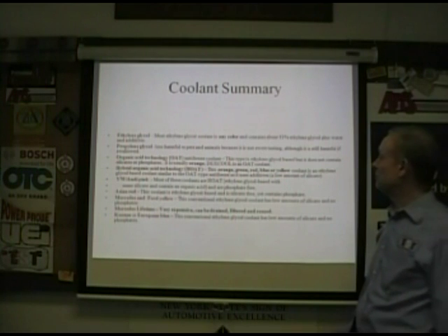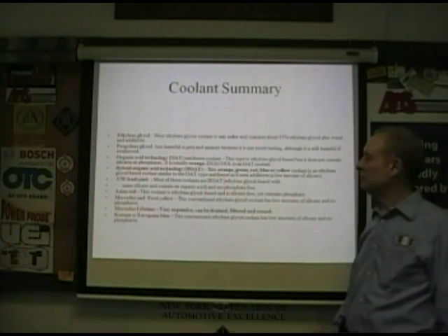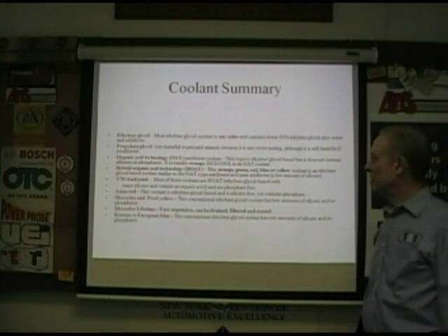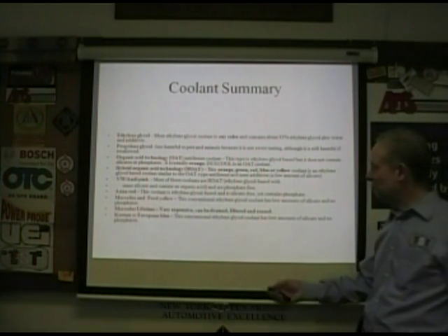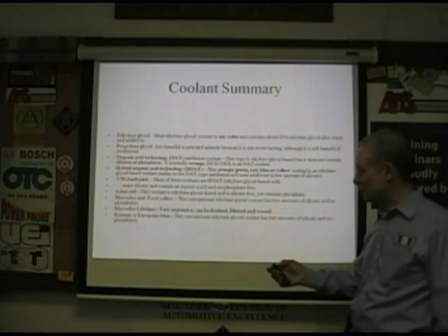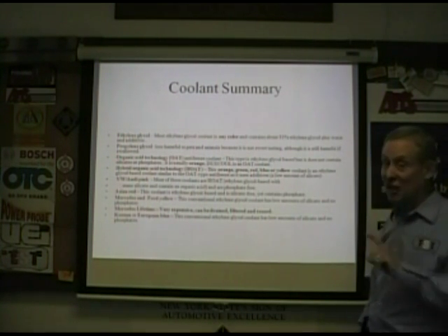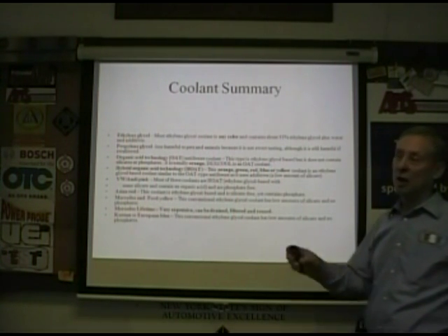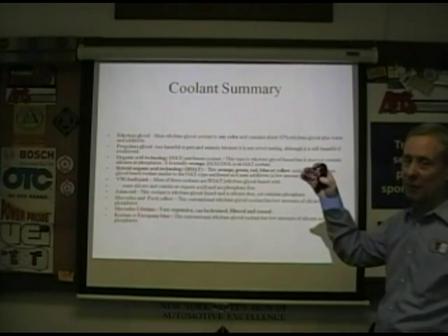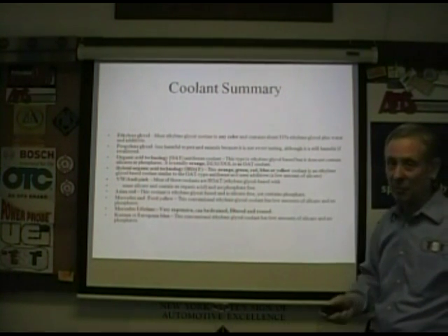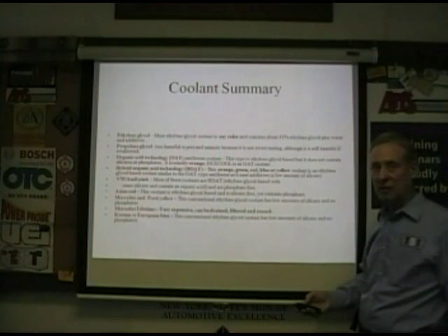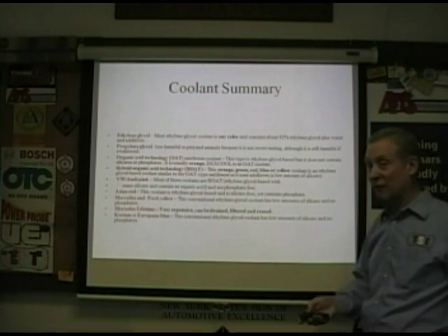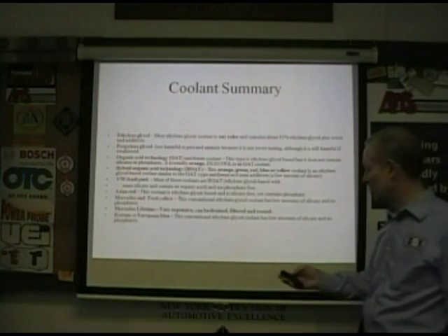It comes in a variety of colors. The color is only a dye. Actual ethylene glycol is clear. It's colorless. You have all these different additive packages for these manufacturers, and they all have their own specs, and the specs have changed over the years. As a rule, I think it's pretty much universal, every manufacturer that's come up with a new spec has made sure that it was totally backwards compatible with their old stuff. Unlike oils, where there might be a little difference, with the coolants, I'm sure that's actually true. They meet all the old specs.